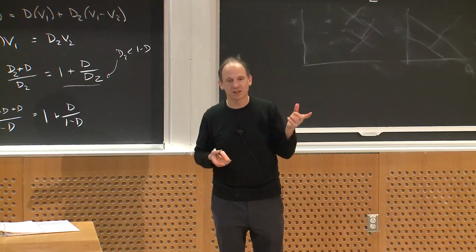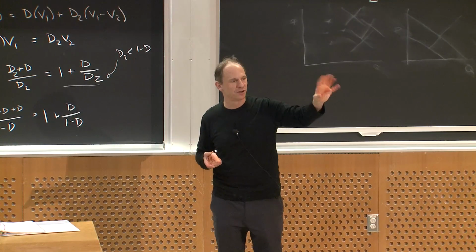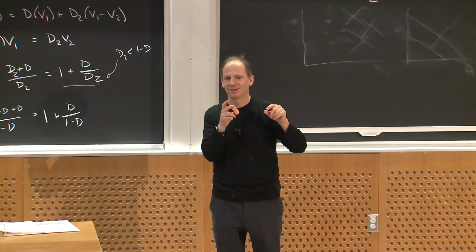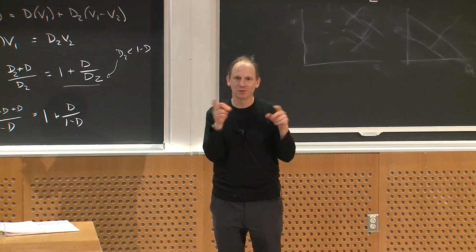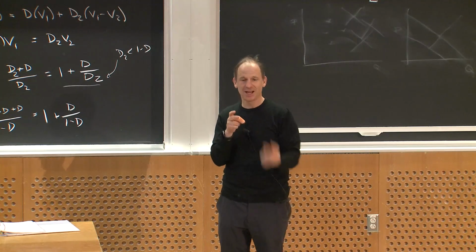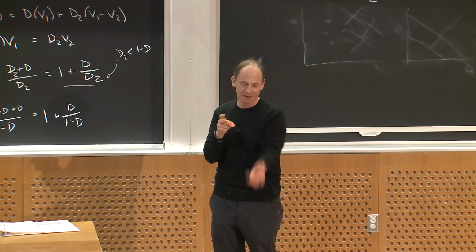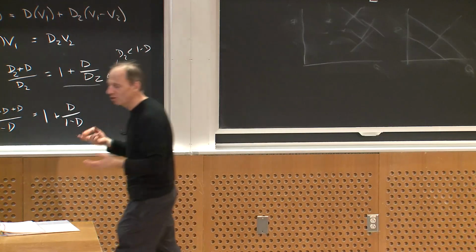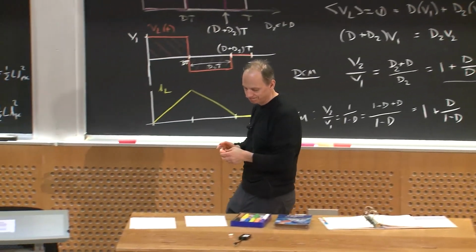In fact, look at little photo flash chargers for those little cameras you use at weddings, the actual film cameras. They often use a boost or a flyback in DCM to charge the output voltage up from like a volt and a half up to a few hundred volts. Same trick. You can get to very large conversion ratios this way. All right.